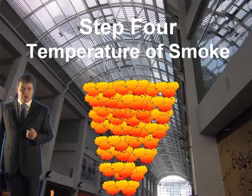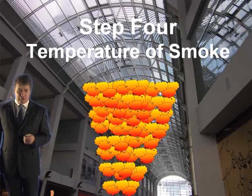Now there is a downstand, and this will cause more entrainment of smoke as it passes under it. So it's conventional to double the mass flow rate of smoke if there's a downstand. So in this case, you should assume that the mass flow rate of smoke out of this shop is 18.81 times 2, which gives you 37.62 kilograms a second. So that's the amount of smoke we've got to assume is coming out of that shop into the small reservoir. That covers step 3. Let's move on to step 4 now, determining the temperature of the smoke.